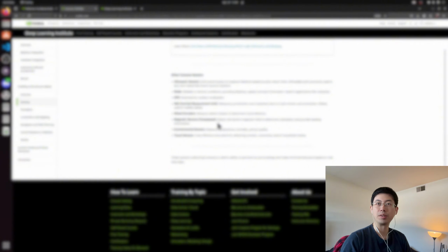And then what else? Other sensors include ultrasonic sensors. You have radar, GPS, which we mentioned before, IMU, and wheel encoders. Wheel encoders measure your wheel spinning rate. Magnetic sensors are more like a compass. They measure the Earth's magnetic field, and that's useful in large outdoor settings. Indoors, you're subject to different magnetic fields. I think drones and missiles actually use magnetic sensors, so they know which region of the Earth they're in. And there are also touch sensors. So when a robot is trying to grab something, how it knows the temperature of it, the pressure of it.